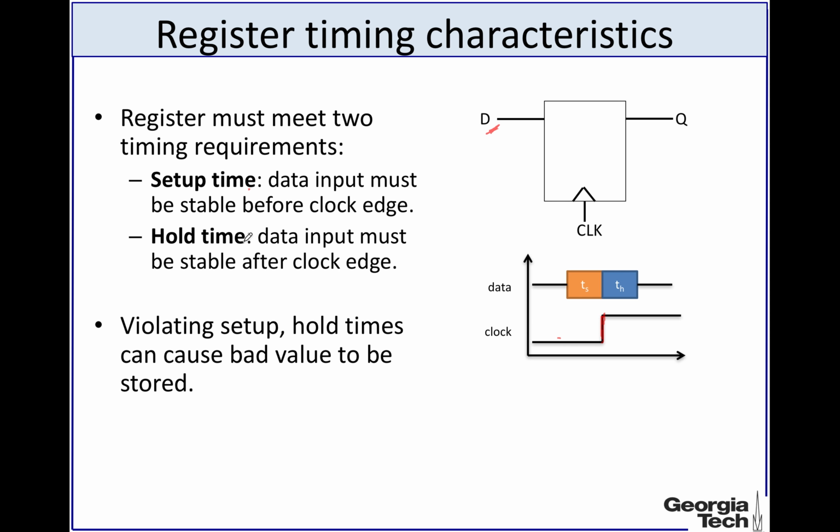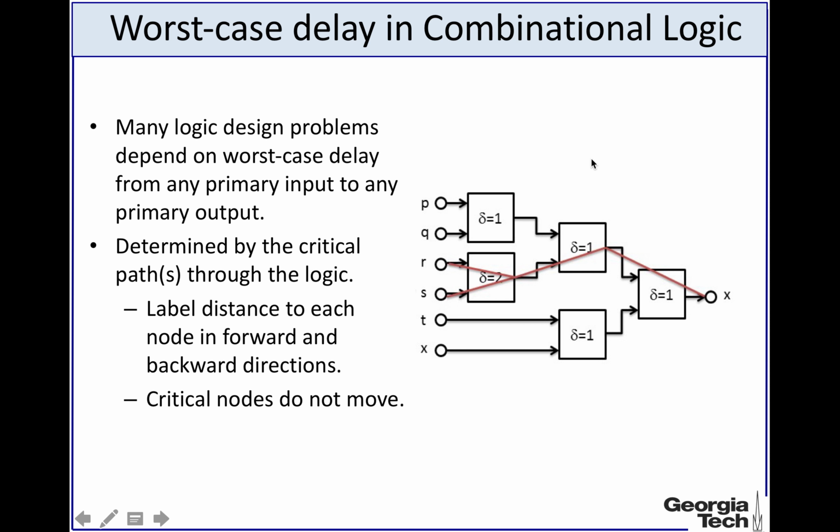And an important thing to note is that if you don't maintain the setup and hold time requirements, the flip-flop will not work properly. All right.